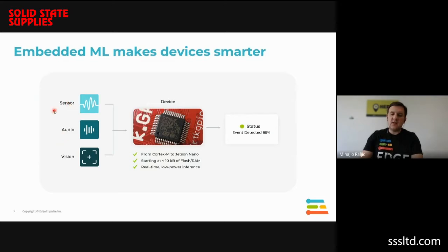There are use cases on which we are working at the moment, and one of them is welding quality analysis. We have sensor data measuring the current during the weld process, the sound of the weld, and the thermal image, in order to tell if a welding process run by a robot is a good one or a bad one. And even after you've done that, you can say what was bad with it.